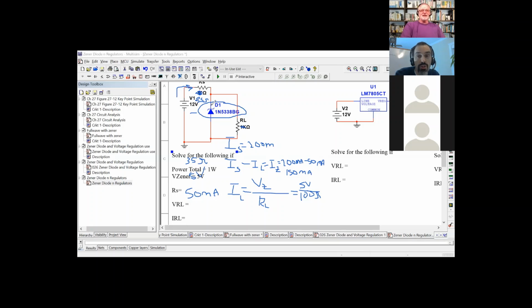That's correct. Yes. You always want to give it at least, I think the recommendation is at least 50% more voltage than your Zener or any regulator is. That's being safe. It gives you a little bit of a safe boundary to play with. Okay, thank you.